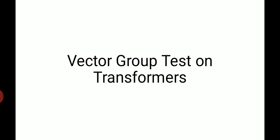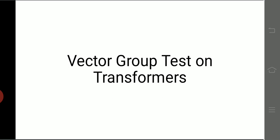So, normally the secondary voltages of a three-phase transformer may undergo a phase shift of either 30-degree lead, 30-degree lag, 0-degree or 180-degree reversal with respect to line or phase to neutral voltages. So, when you refer to the nameplate ratings of the transformer, you always come across vector groups.